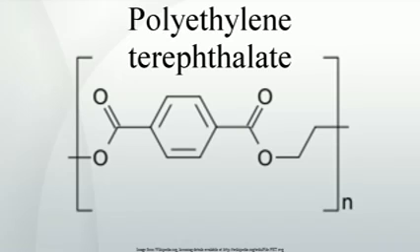The fact that some machine manufacturers and line builders in Europe and USA make efforts to offer independent recycling processes, for example the so-called bottle-to-bottle, B2B, process, such as BPET, Starlinger, URC or Bula, aims at generally furnishing proof of the existence of the required extraction residues and of the removal of model contaminants according to FDA applying the so-called challenge test, which is necessary for the application of the treated polyester in the food sector. Besides this process approval, it is nevertheless necessary that any user of such processes has to constantly check the FDA limits for the raw materials manufactured by himself for his process.